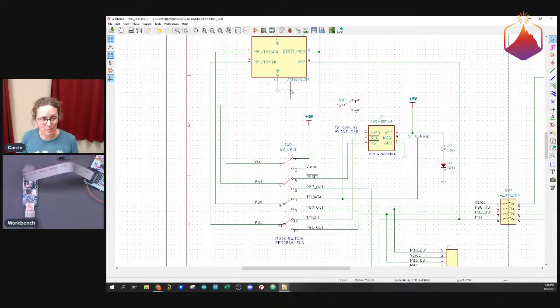So that's how you use the USB ASP with it. If you have an old school original AVR ISP Mark II that was legitimately produced by Atmel, it will talk TPI natively out of the box. But they discontinued that programmer because, I don't know, it was too cheap and convenient. So now there are a whole bunch of Chinese knockoffs, and none of them talk TPI. If you have an old original AVR ISP Mark II, which I happen to have because I'm cool, it will talk TPI. But wait, there's more.